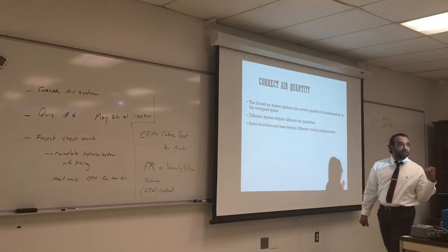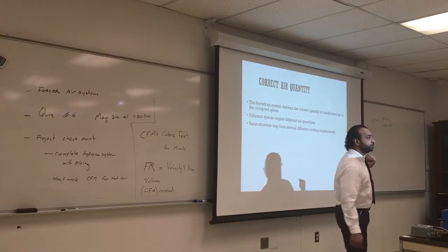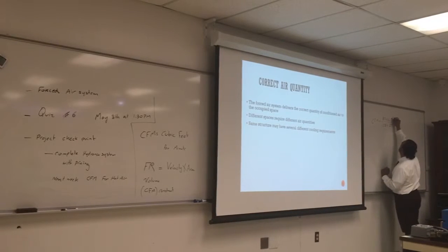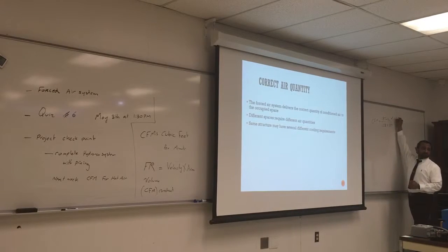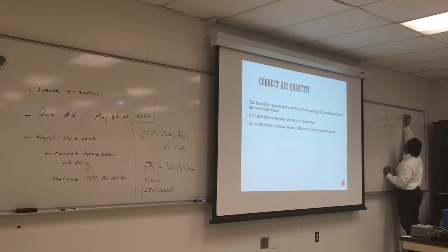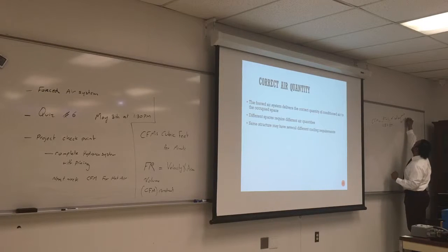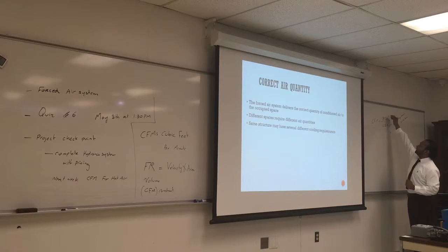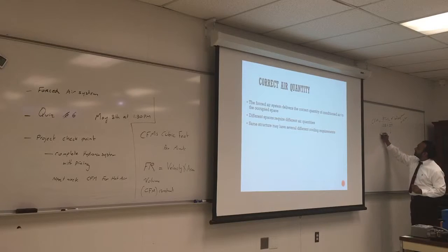This is the air quantity you need to deliver to each room to maintain temperature. So what is the BTU here? Heat requirement. Is the CFM going to be the same for both heating and cooling? Yeah, but the change is going to be the delta T and the BTU for cooling. Okay, yeah. 1.08 is constant.